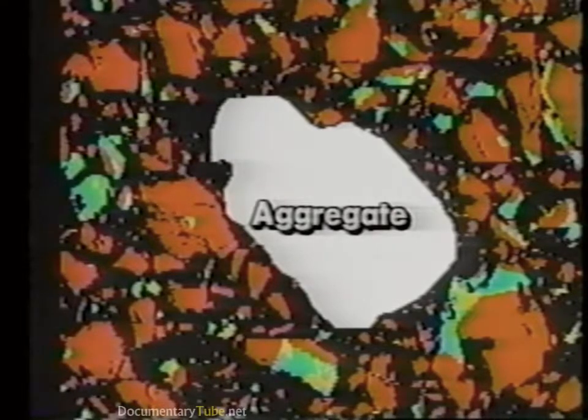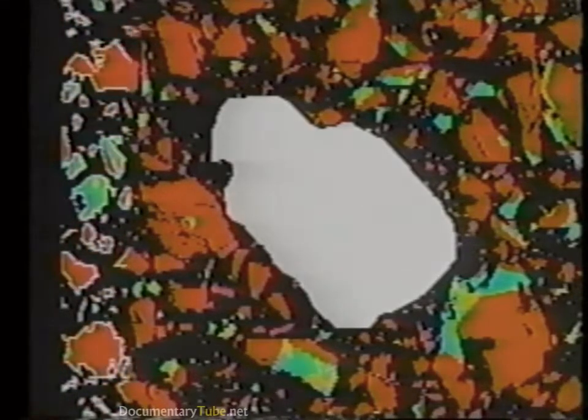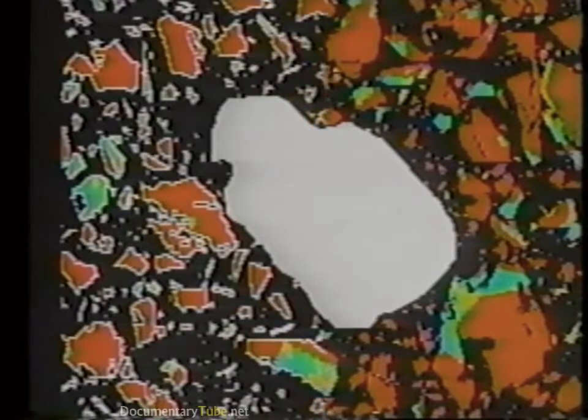Before the hydration simulation, particles of cement are arranged on the computer display. The computer determines regions of the particles that can dissolve into water. The bits of dissolved cement diffuse through the water in a random manner and react to form solid phases according to certain rules.